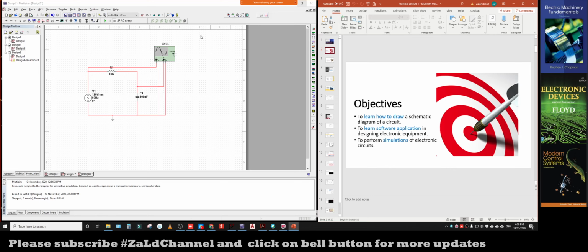Make sure you construct just one part of your sensor first. Sometimes during your experiment you will burn some component, for example. Then if you want to order, you can order it all together. So make sure you first construct the first sensor module. If you manage to run it successfully and test it, then you have to find another two pieces of the IR LED and also the photodiode.